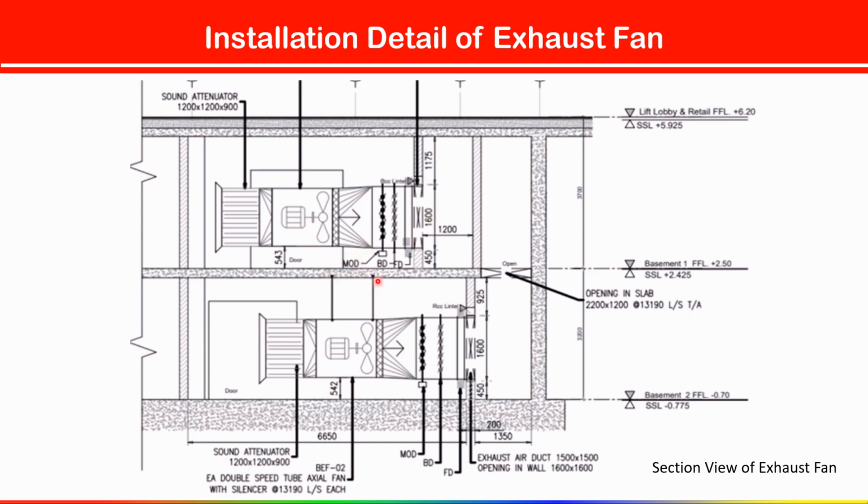Then after that we have a backdraft damper. The function of this backdraft damper is that it allows air to flow efficiently through the exhaust duct to the outside, and it prevents the unwanted flow of air into the basement when the exhaust fans are off.